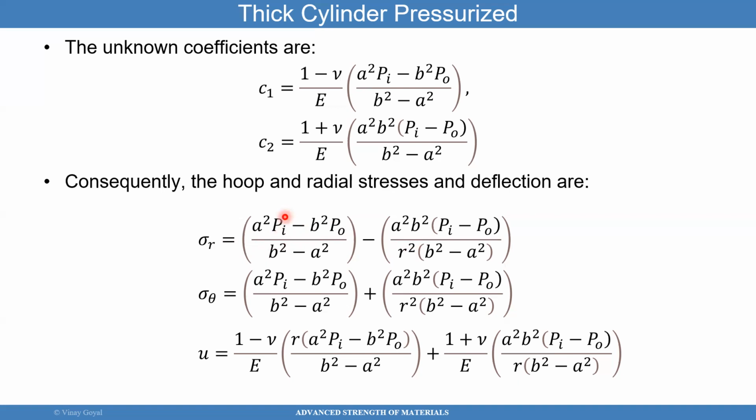Is that making sense to you guys? Is it connecting? Then when you look at the deflection though, you get the Poisson ratio involved and you get the modulus involved. But everything else is known. And the only thing that's not known is R, but R is the one that you want to plot that radial deflection versus R so you can see how the cylinder expands, right? You can plot that now.